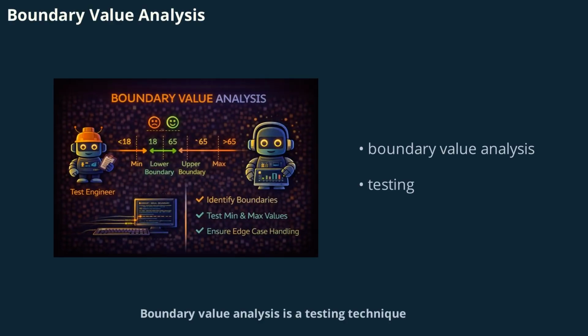Boundary value analysis is a testing technique that focuses on the edges of input ranges, where many bugs tend to occur. In embedded systems, testing at minimum, maximum, and just above or below these values helps ensure robust error handling and system reliability. This approach is crucial for catching issues related to data type limits, overflow, and extreme operating conditions.